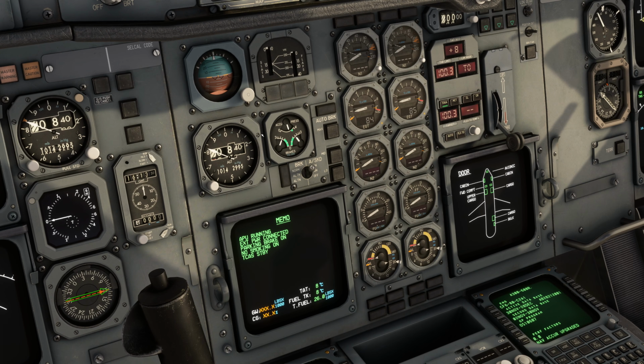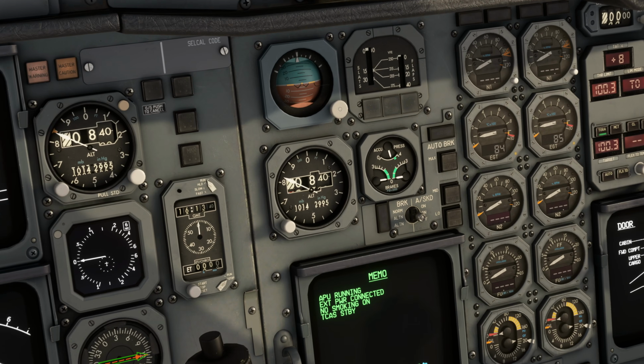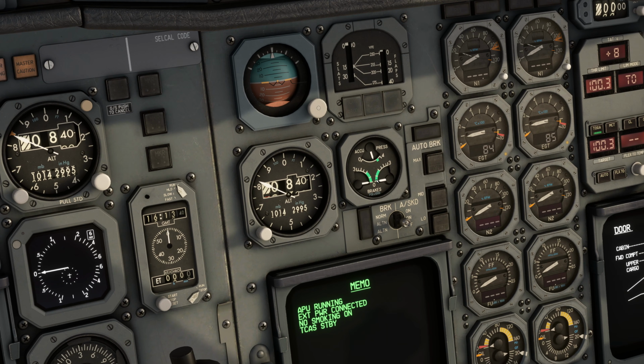So, this is the original position that we are going to be in. Park and brake and any-skid switch is normal and on. Now we go to alternate on and we release our park and brake. You can see that the brake pressure indication is now going down. Now we're going to apply our brakes manually, and we make sure that the pressure is rising symmetrically and without delay on both sides. Like that.